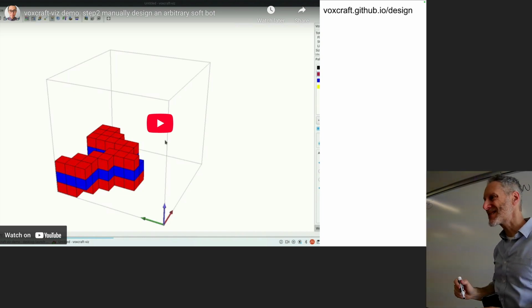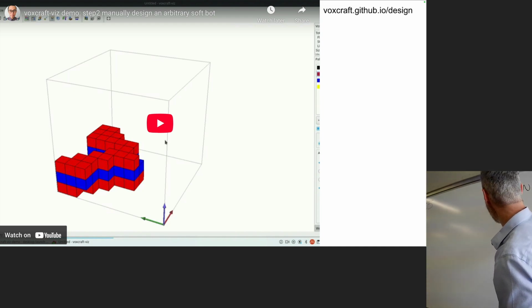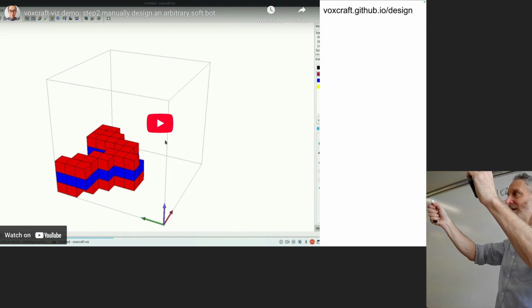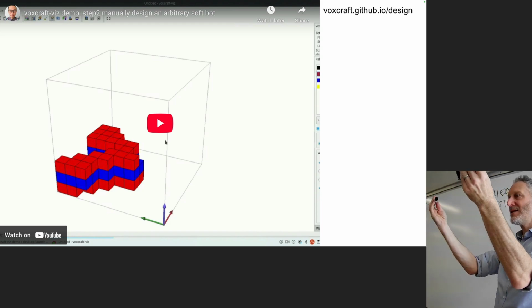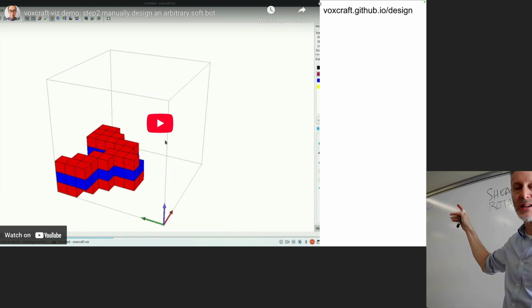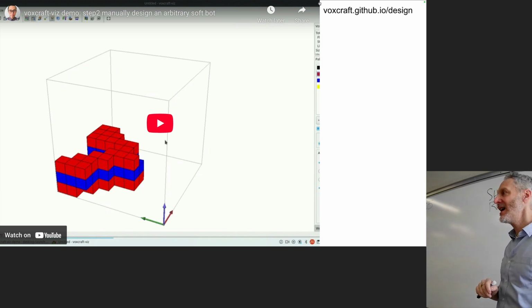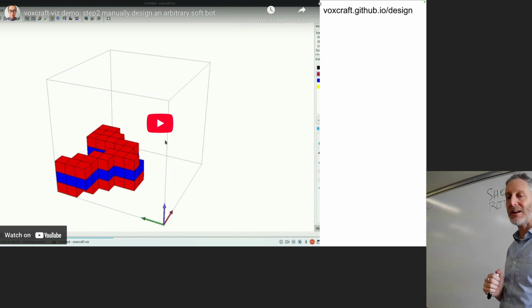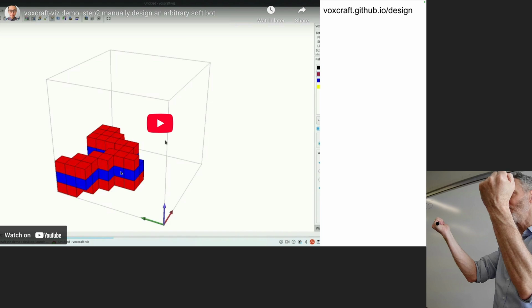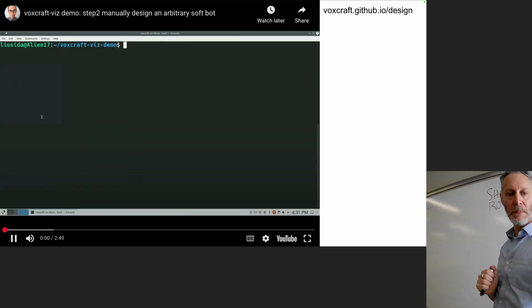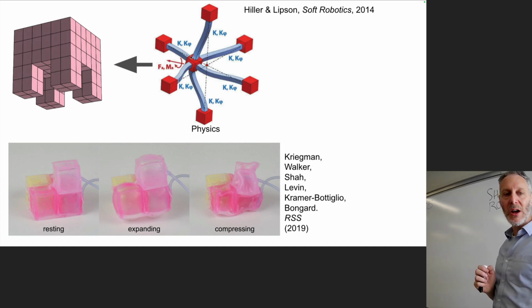The 4th, 5th, and 6th numbers describe how much the beam resists 3 different kinds of rotating. This, bending, this one, and this one. Yeah? So every pair of cubes that you see here, there's a little beam hidden inside, and some of these are rubber beams. They allow the 2 ends to move relative to one another quite a bit. Some of these beams are more like steel beams, and they're resisting shearing and rotation quite a bit. Okay, so I described all of that last time.